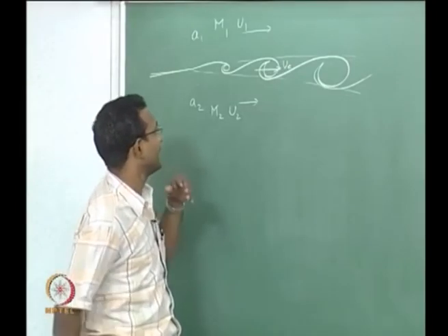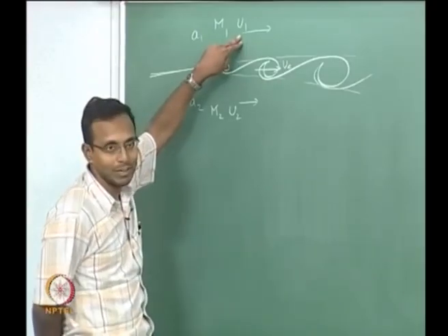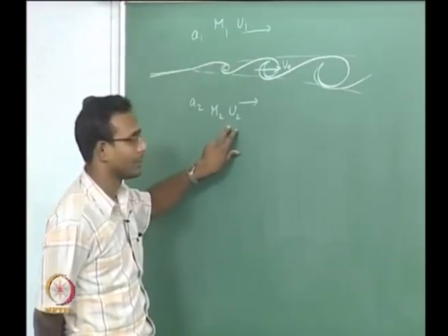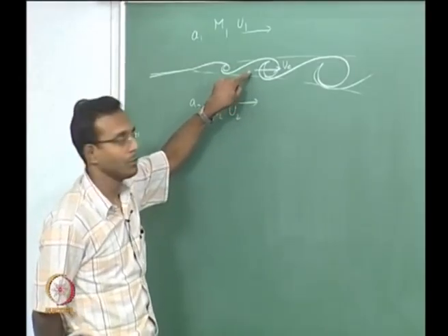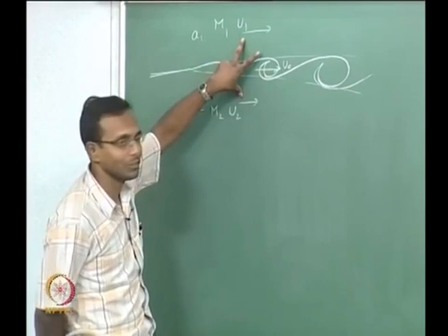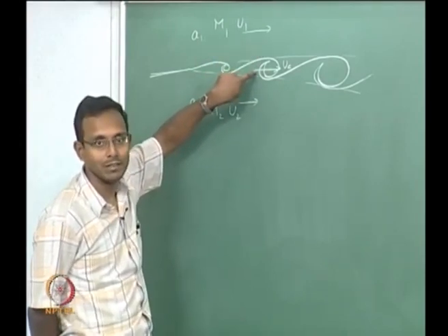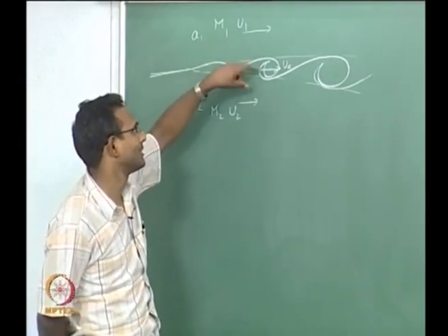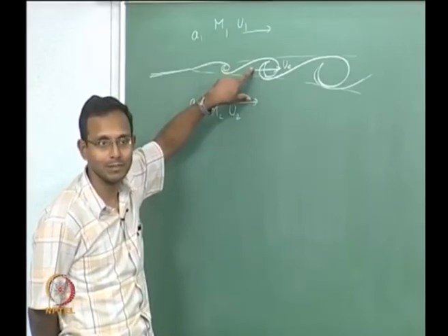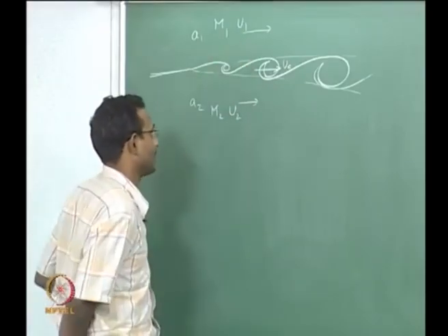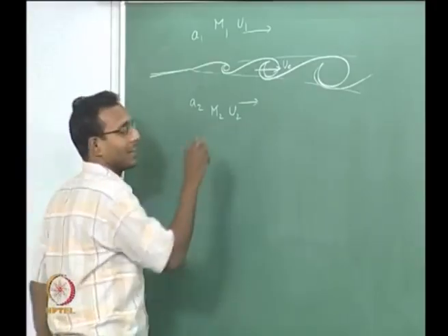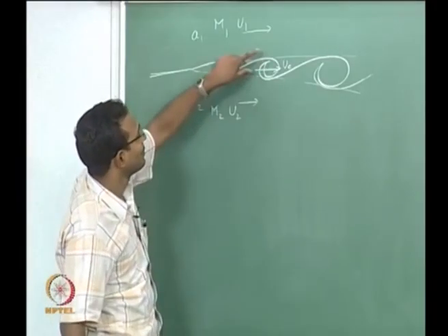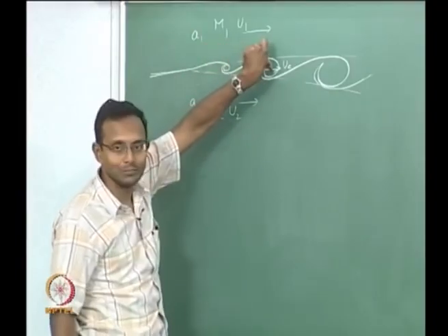They are going to say that U1 is some high value, U2 is some low value, UC is some intermediate value. Okay, because that is caused by these two differences, it has to be something in the middle, which you know from your velocity profiles also that this value will be roughly close to the middle average of these two values. Okay. So, they started defining things like relative velocity of the fluid with respect to this structure.